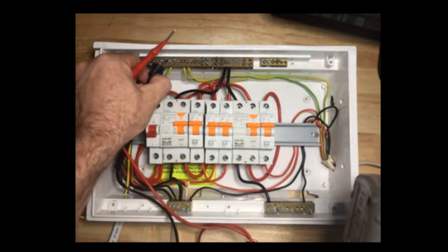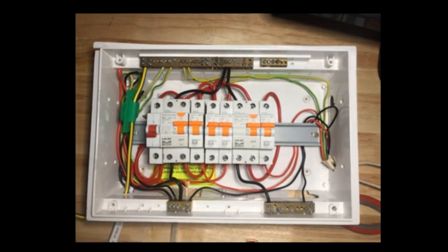I've now proven that everything that is connected to this installation has passed its insulation resistance test. What I'm going to do next, if this was a real installation, I'll put my earth neutral link back in. And provided I've safely passed the other tests required before I liven an installation, now we're able to liven and start the live tests. And those other tests will be described in other videos.